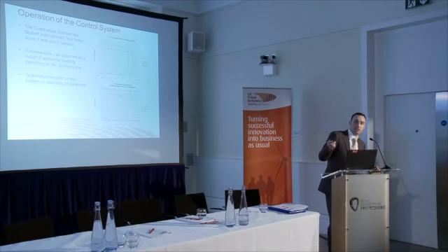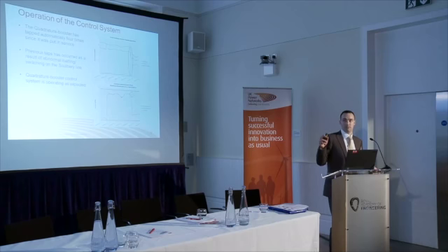And the second operation occurred on the 23rd of September, around midday again. What isn't evident from the bottom graph is that the deviation actually met the upper threshold, which would initiate the tap. And the reason is that I mentioned the data that we have is averaged over 10 minutes. What you can see from the top graph is that at the time of the tap, the load on the Sudbury circuit actually significantly increases. So the 10-minute averaging actually masks that.